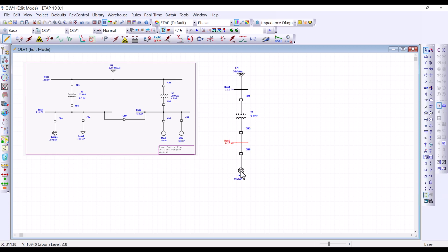I want you to note the selection of the bus was reactivated, and now ETAP knows that I'm done at this point, and it takes me straight to bus 2 to add other components to the right of it. That would be my other breaker, and then a static load. Okay, now we're done with the left side. Let's do the right side by extending this a little bit, and let's add a breaker. Let's move that a little bit here, and then we'll add a 2-winding transformer, another breaker, and then a bus. Let me add the cross tie here, and then